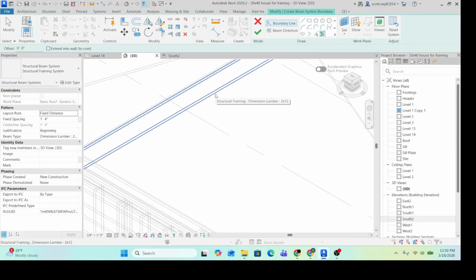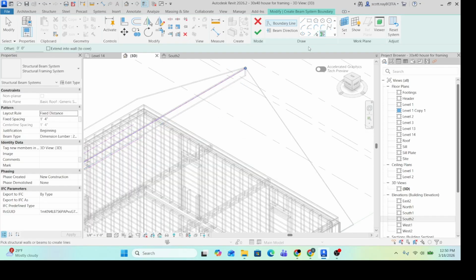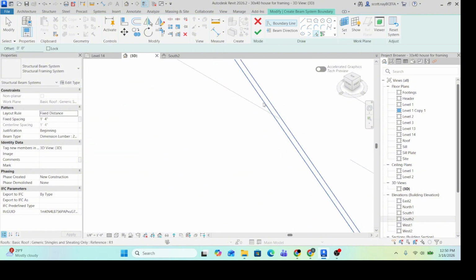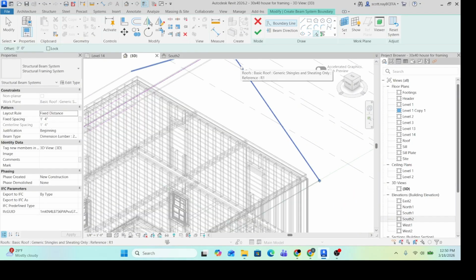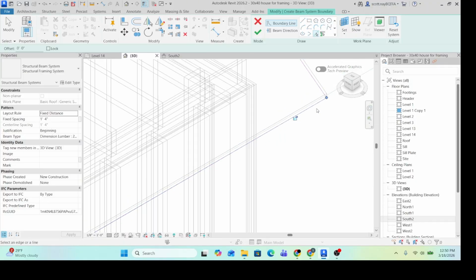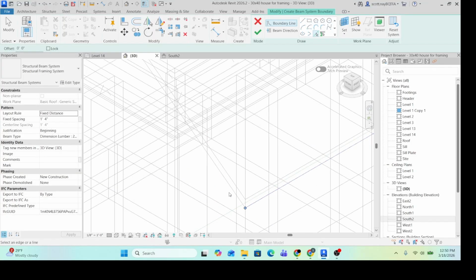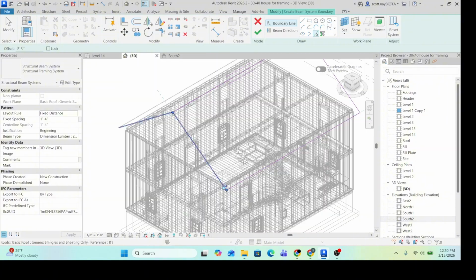I'm going to start by just picking this. So now I got one boundary. And now I can say pick lines. And I want to pick, again, the lower. Click tab, get that lower line. And now that we have one, it should automatically snap close to that.